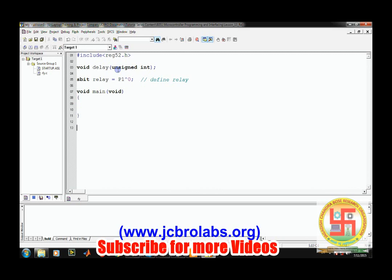Now let's define this delay function, void delay unsigned int t, and now define unsigned int i, j, and then two for loops: i equals 0, i less than t, i plus plus, and then another loop for j equals 0, j less than 1275, and then j plus plus. So we'll simply turn the relay on and off. So first make an infinite loop,